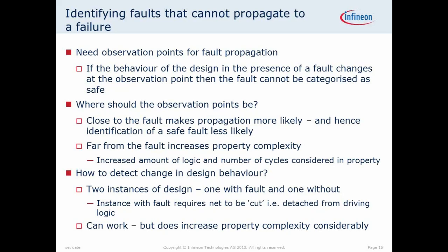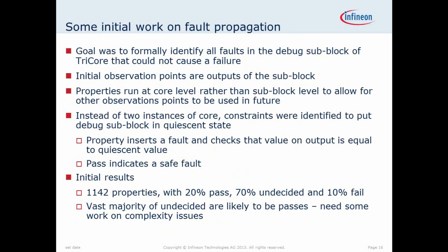Next question is how to detect a change in design behavior. So perhaps the most obvious thing you can do is just take two instances of the design, put the fault in one, not in the other, and see if you get a difference in behavior between the two. That's fine, it does work, but again, because you have two instances of your design compiled into the tool, the complexity increases somewhat.